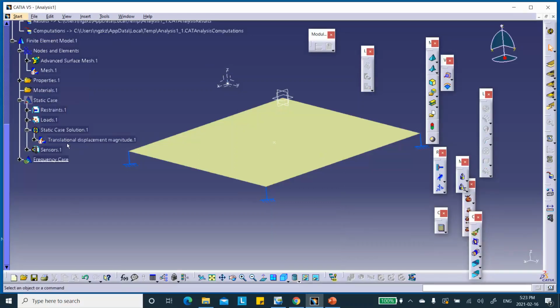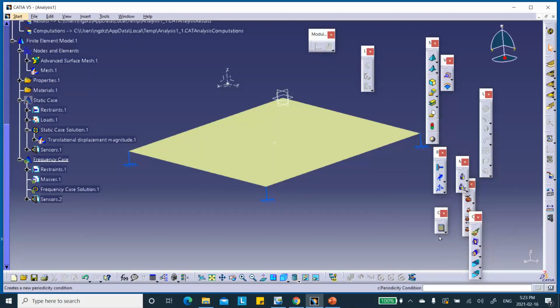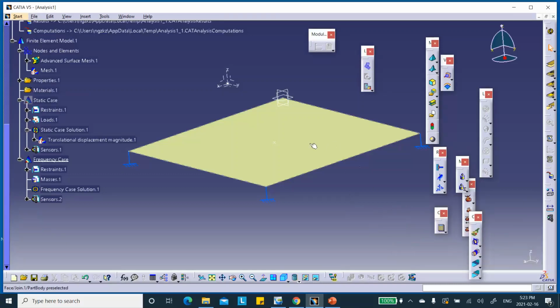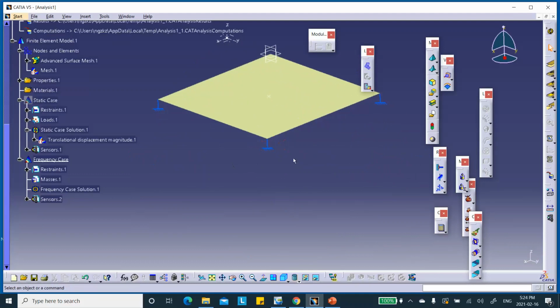Nothing fancy. It's going to extract 10 frequencies by default. You can see that if you double click on this, the default is 10 frequencies. That's okay. We just leave it the way it is. And we're going to run it. Again, nothing exotic is going to happen. It's going to extract 10 frequencies, and we can plot the mode shape. Now, remember, this is one of the more expensive steps in the calculation that we're doing. But 10 frequencies is nothing. So, all right, let's check it out.